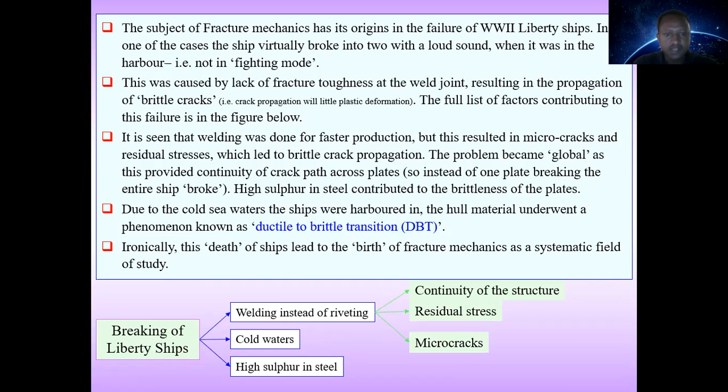Due to the cold seawater where the ships were harbored, the hull material underwent a phenomenon known as ductile to brittle transition. Ironically, this failure of the ships led to the birth of fracture mechanics as a systematic field of study.